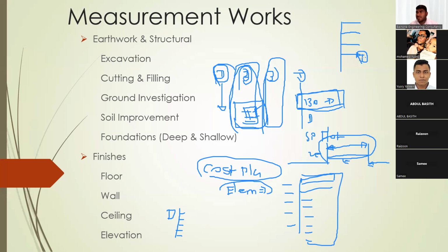Based on the questions, if the engineer or the QS feels that sufficient documents are not given to the contractor to price this, you ask the designers or engineers, and you add some more documents. The documents you issue to the contractor during the tendering phase are called a tender addendum. Addendum means extra documents you are giving to them. This is also the quantity surveyor's duty.